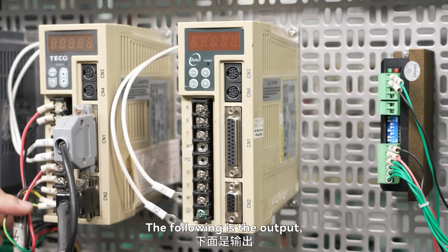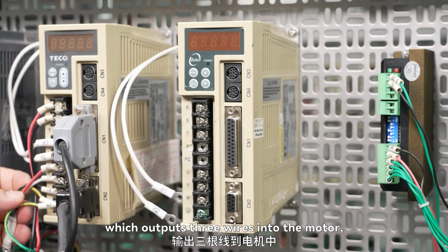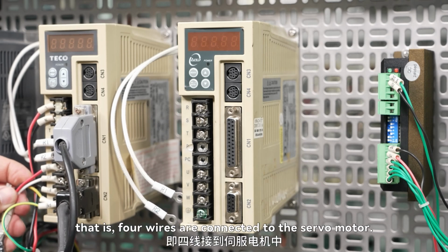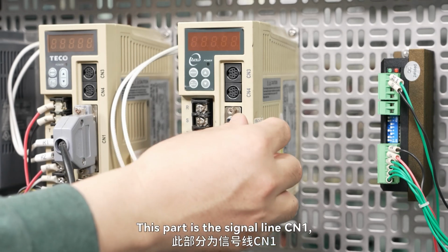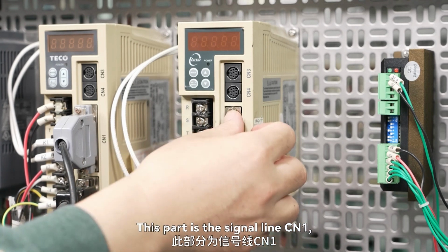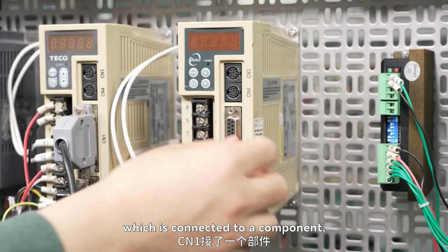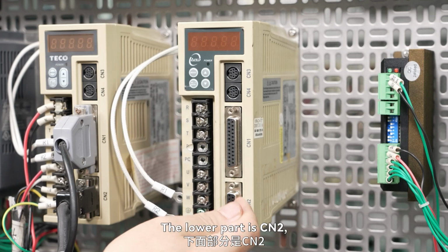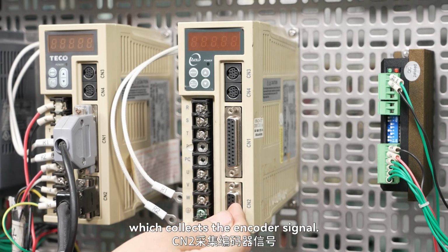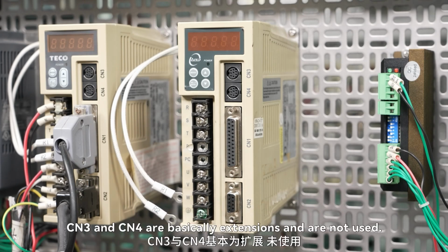The following is the output, which outputs 3 wires into the motor, that is, 4 wires are connected to the servo motor. This part is the signal line CN1, which is connected to a component. The lower part is CN2, which collects the encoder signal. CN3 and CN4 are basically extensions and are not used.